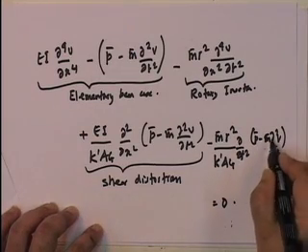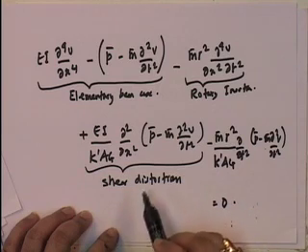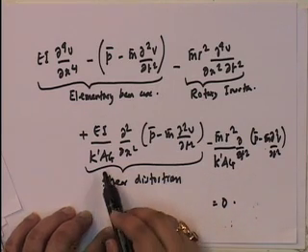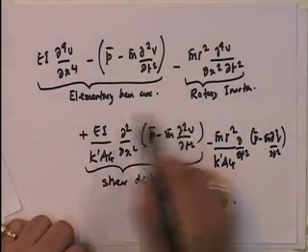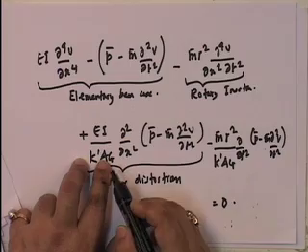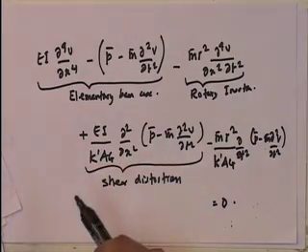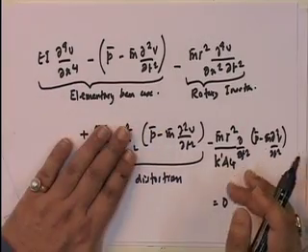Now, if you look at this, what is this? This one is purely shear distortion. Because if this becomes infinite, this disappears. Remember that if shear distortion is to be neglected, you are to assume that k prime a g is infinite. If this is infinite, this goes to 0. So, this is purely shear distortion.